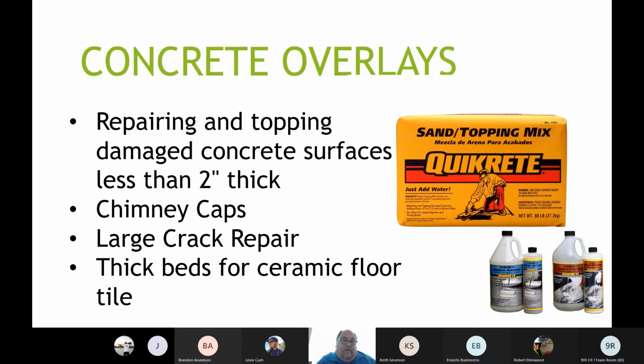So you don't need to fill the crack with this. You just need to seal it. So put a backer rod in there, give yourself about a 1/2 inch wide, 1/4 inch deep seal, and it'll be just fine. Thank you.